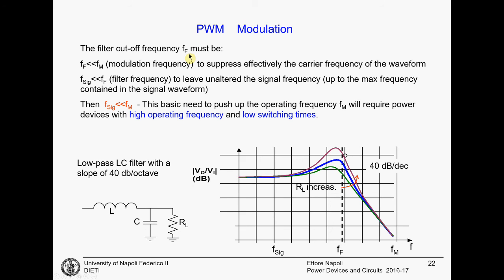It is then clear that since this is a low pass filtering circuit, the zero frequency, the DC component, passes unaltered, because at very low frequency C is an open circuit, while L is a short circuit, hence the input goes directly to the output. At very high frequencies this becomes an open circuit and this a short circuit. This means that the input signal cannot pass to the output.